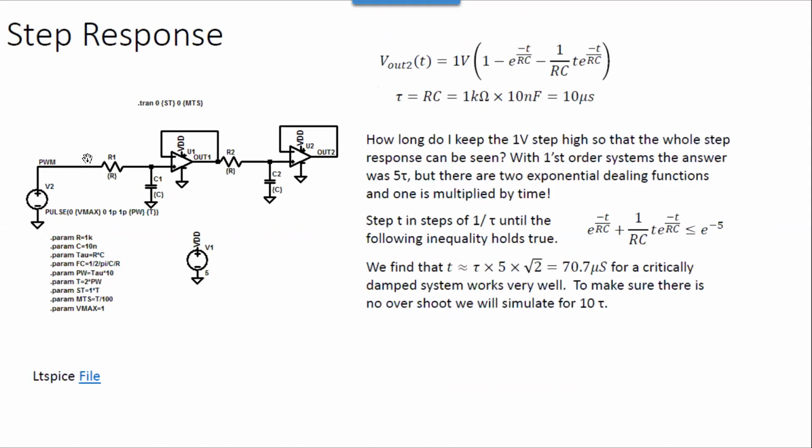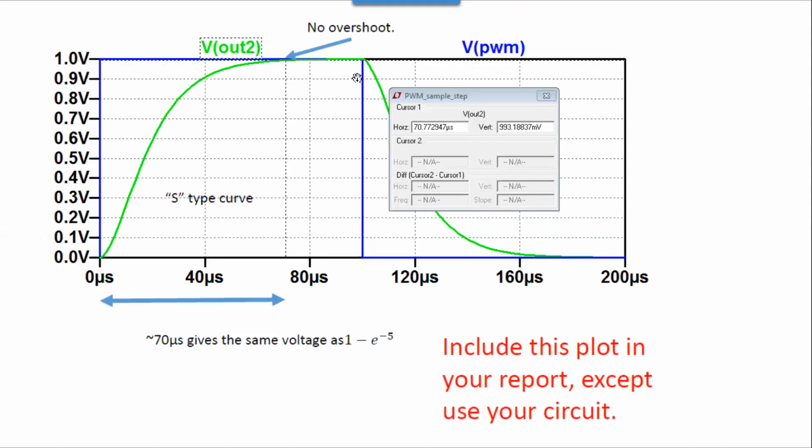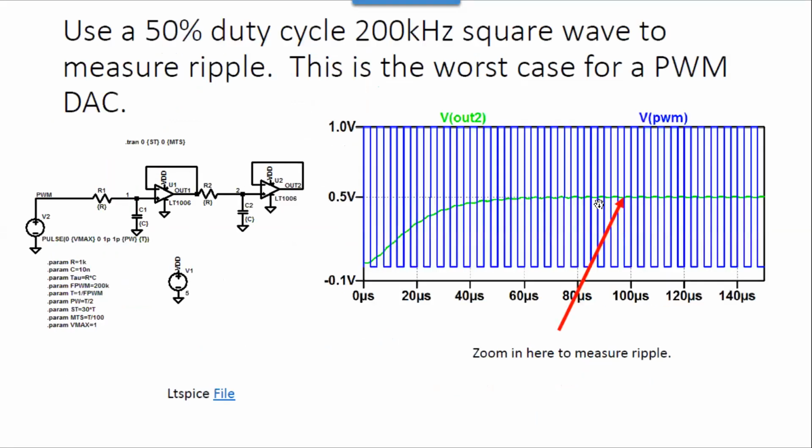Just for example, we've got a low pass filter here. We're going to do the step response, and we see it goes up and it comes down. Notice we're giving this enough time to rise all the way up and all the way down. This here would be the frequency of the pulse width modulated signal. It's not the duty cycle, it's just the frequency of it. If we start turning that off and on faster, you can see that it's starting to ripple up to its average spot.